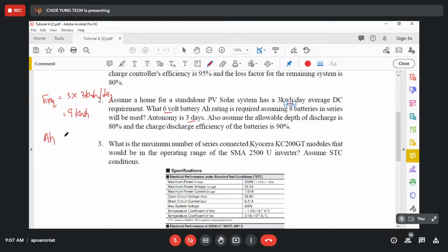But it's not in watt hour. To convert from milliampere hour to watt hour, you have to multiply with the voltage output. For this case, the battery has a voltage output of 6 V. For your power bank, I think it should be 5 V to charge your headphone. Based on this, maybe you can do it this way. The AH rating, 6 volt, and a total of 8 batteries. So I have 8 batteries with an AH rating of unknown and a voltage of 6 volt.